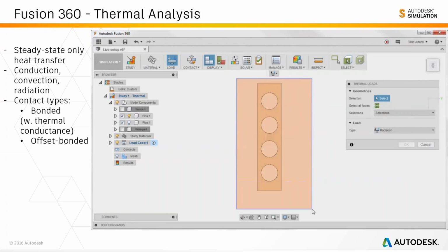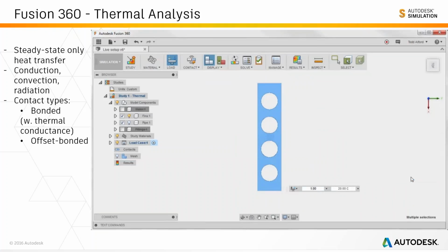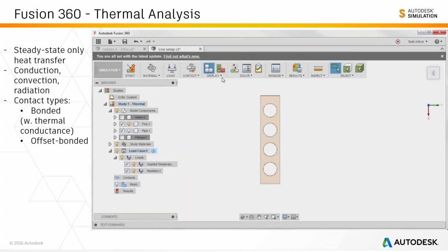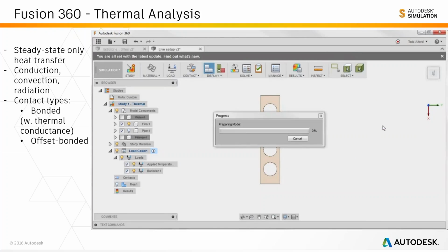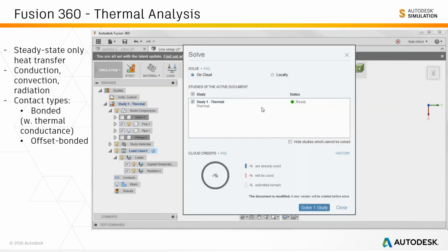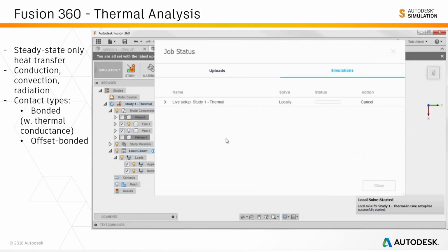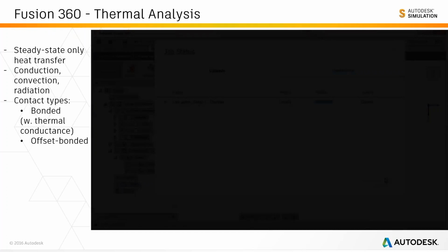As well as the main heat dissipation mode here, radiation. So we're selecting the surfaces of the fins minus the surfaces in contact with the hot pipe. So we're subtracting those, and we're assigning a radiation boundary condition. Automatic contacts will ensure that these parts are touching. If the contact there has no input in the thermal resistance, that means it's a perfect contact, no resistance there.